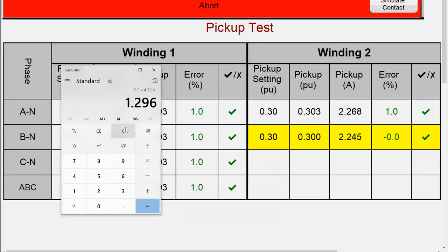But if you remember on the differential screen, I showed the single phase pickup factor. Because we are performing a single phase pickup factor, and there is a factor of 1.732 that we used, I need to multiply that factor along with this calculation to arrive at the right test value. So 2.25 is where my relay is supposed to be tripping, or anything more than that, it's going to trip. If you look at these numbers, that matches to our calculation here.